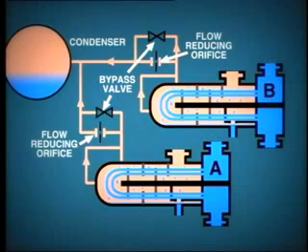This valve should be opened during startup and closed when the unit is placed online at minimum load. In the example shown here, both low-pressure heaters are vented to the condenser.